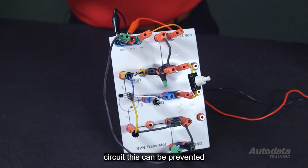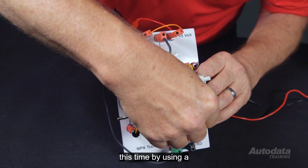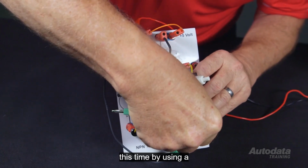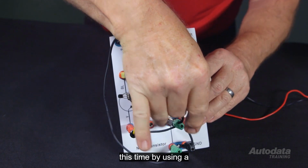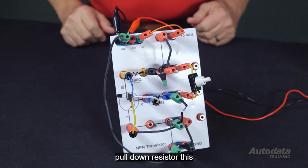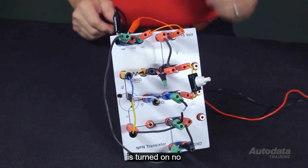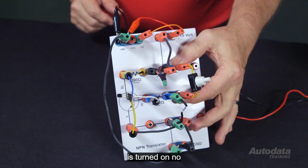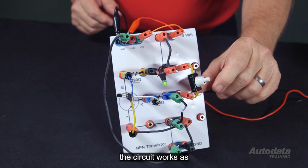This can be prevented this time by using a pull-down resistor. This now holds the base circuit to ground until the switch is turned on. No more false triggering, and the circuit works as it's supposed to.